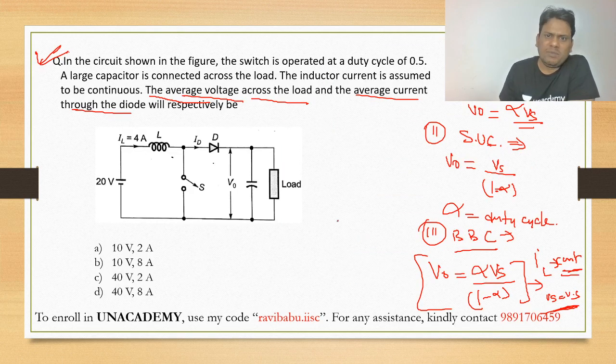Now dear, tell me the name of this converter, the name of this chopper circuit, everyone. Dear, the name of this chopper circuit will be step up. Why will it be step up? Because dear, in a step up converter, we have the inductor in series with the supply. Okay, this is our supply.